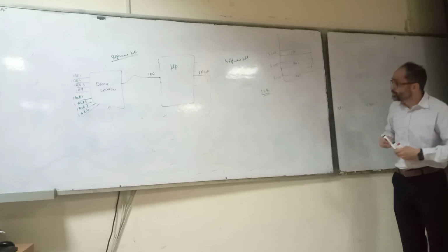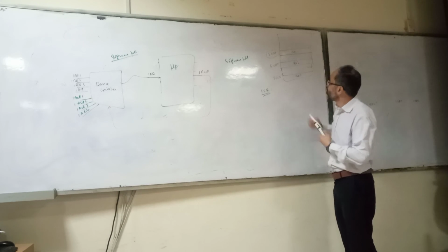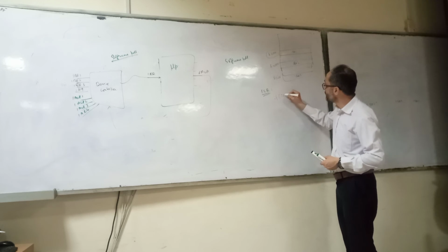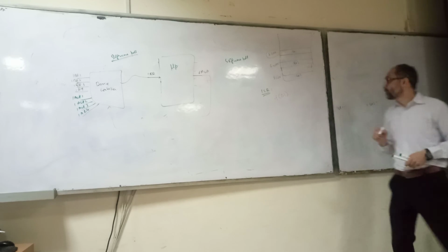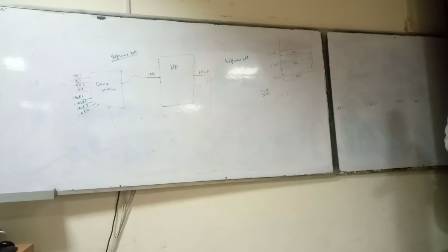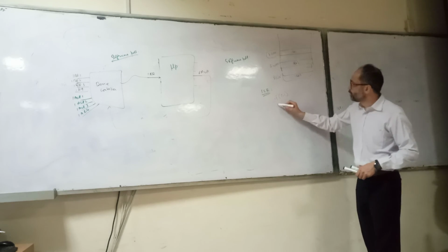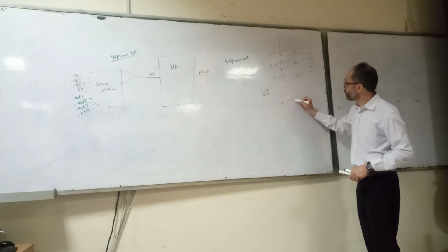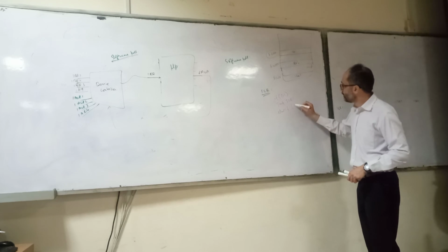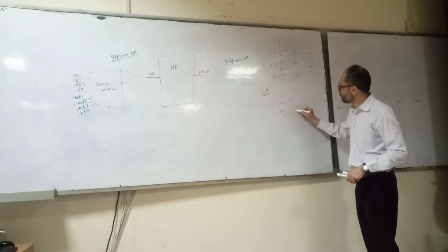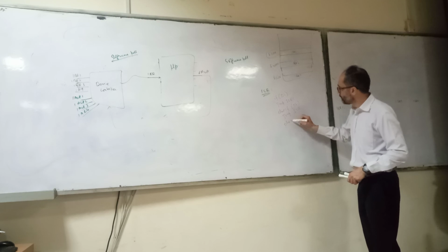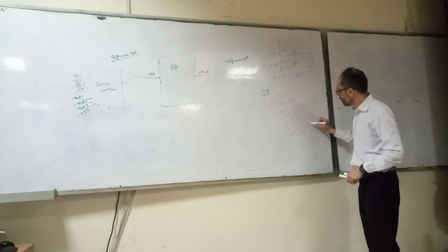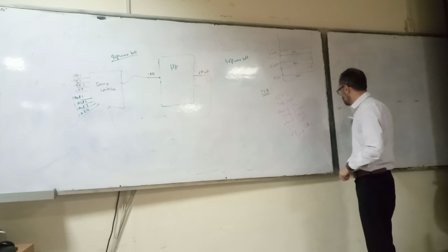So when it jumps, what will the processor do? It will ask if D1 has generated an interrupt. If device D1 has generated, where should it jump? Jump to ISR1, else if D2, jump to ISR2, else if D3, jump to ISR3, else jump to ISR4.